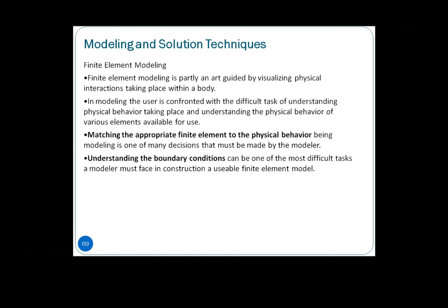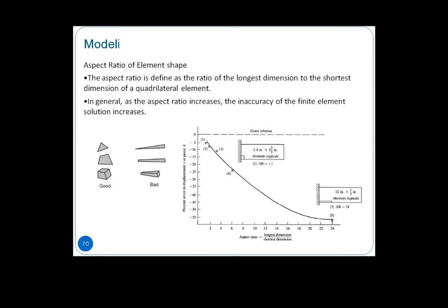So matching the appropriate finite element to the physical behavior is one of the challenges. Because we are already in approximation under this finite element analysis method, which is a numerical approximation, we want to get as close as possible to the actual or exact solution. In this case, the most challenging part is how to match this particular finite element model to the actual physical behaviors. So that is one of the challenges of finite element modeling.